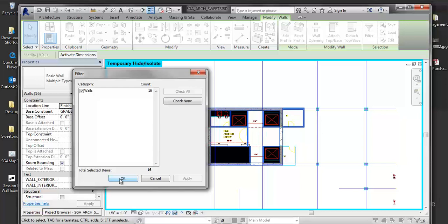If I have a varying floor height, like that mechanical floor, there's going to be a separate group. A group is like a block. If I edit one element inside that group, it's going to update all the other groups. So being really aware of this is when we'll actually figure out those levels too.